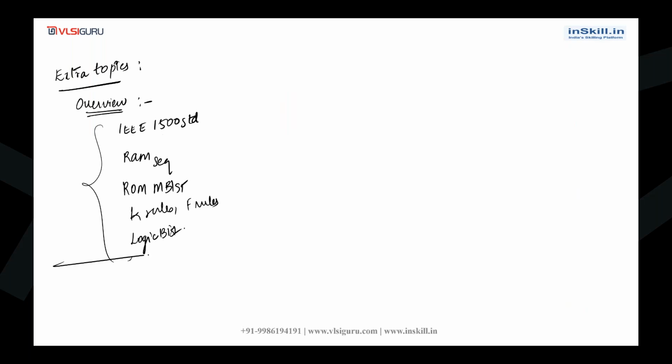Okay, and then I will also cover STA. STA overview also I will give. STA is static timing analysis. So it is not a DFT topic. But some interviewers expect you to know some basics of static timing analysis. So what is asked in a DFT interview, like what is setup time, what is hold time, what is setup and hold violation, what are the fixes, how to find out the maximum frequency of operation, or such kind of points, whatever is asked in the DFT interview. Those kind of questions I will cover in the STA topic.